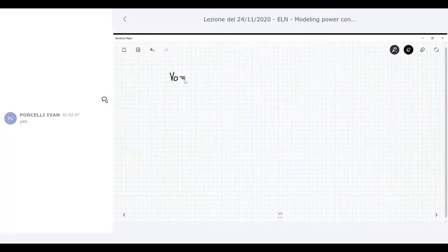Now, when you take the square root, you can choose between the plus and the minus sign, and the good sign is the minus. Remember that V naught has an opposite polarity with respect to that of V in. So V naught requires a negative sign here. So this is V in multiplied D, then you have R over 2 L Fs, under the root.